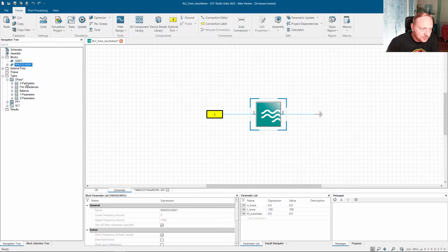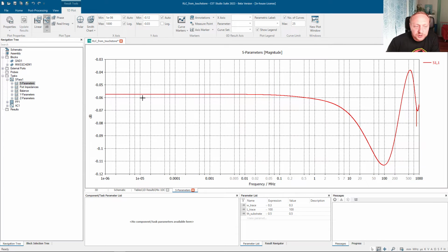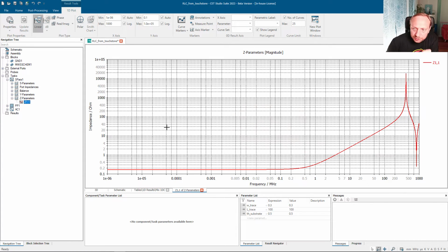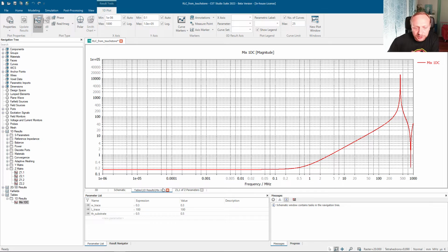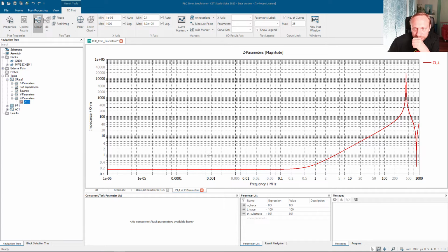And if I calculate the S parameters, obviously, I don't see something like a transmission because all the signal is coming back. It's flowing in the loop. So the S parameters now are a little bit meaningless. But now I can look at the Z parameters like I did before, and I obtain exactly the same thing, but without typing the formula. I just use the circuit to do the math for me. And I'm getting the same response. You can see that's the response I calculated with my formula. But this is now the Z11 calculated on the circuit just by shorting the other side.